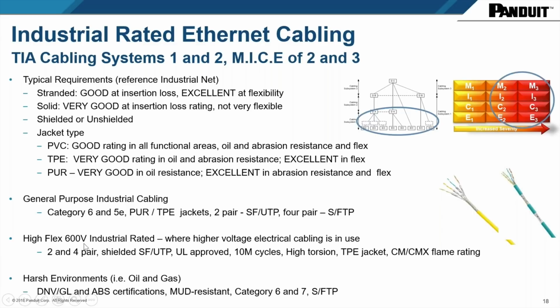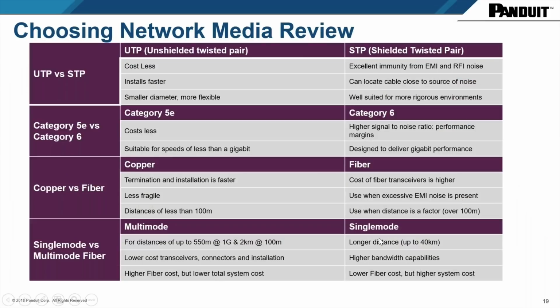When you have high flexing, you have to have different patch cords that can be rated for high voltages around them, that is. All these cables are designed to handle 24 volts, but with the right shielding on the cable, it can be run next to a 600 volt line of power. So that brings me to this table.